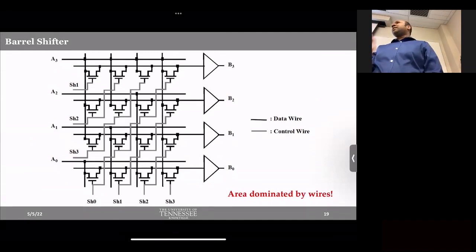Don't get too excited so soon. A shifter can only multiply by certain amounts. It can multiply by 2, 4, or something like that. You cannot have any arbitrary multiplication done with a shifter. The shifter is designed to provide a specific type of multiplication, by a factor of 2, 4, 8, depending on how many bits you're shifting. You cannot have a multiplication by 13, for example, from a given circuit. Okay, am I making sense? But if you are just dealing with a specific type of multiplication, then a shifter is a great option.